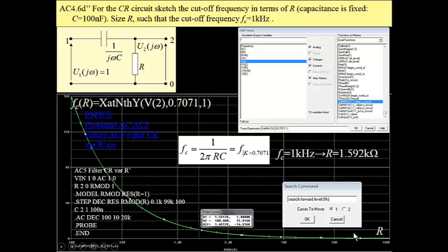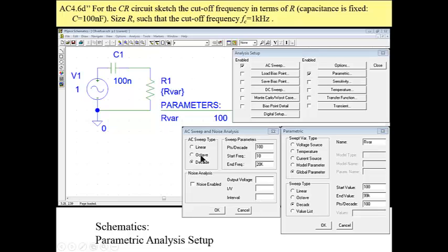We have a curve, a function of cutoff frequency gain. This is gain at cutoff frequency. This unity is meaningless. I'm not going to explain. It has to be there. And then we are searching for the level of 1K, and for this level we obtain here that the resistance is 159K. This is a schematic version of the same.